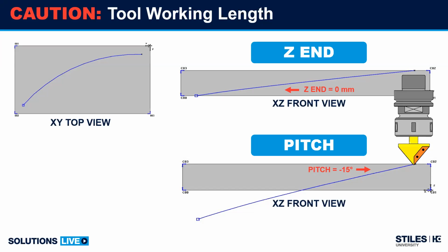That way, when you replace the insert, the angle is always correct. If you get a carbide tool, every time they grind it, if they didn't get the angle exactly correct, whether it's a 45, a 90, or a 60 degree tool, you're going to have to go back and recalibrate that tool to make sure the corners are square. So again, try to get insert tools. It just makes them faster to get back into production. You don't have to recalibrate.